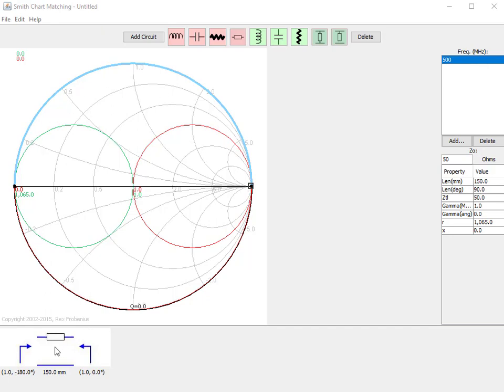And so our component now, instead of seeing a short, because of this length of line in between there, it's going to see an open termination. So our performance is going to be tied to as if the component was seeing an open circuit, which is not at all what we would be expecting.